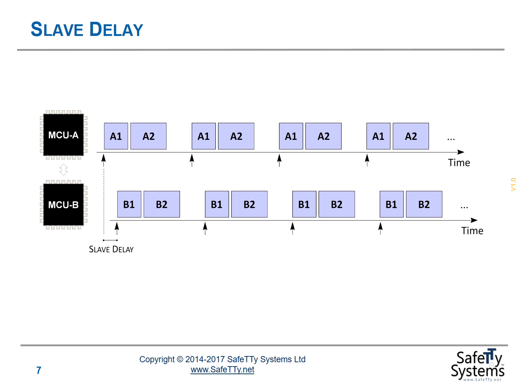Of course, the length of this delay will depend on a number of factors, such as the communication protocol that's used and the baud rate or bit rate of this communication protocol. The slower the bit rate, the longer the delay in the transfer of these messages, the larger the slave delay.